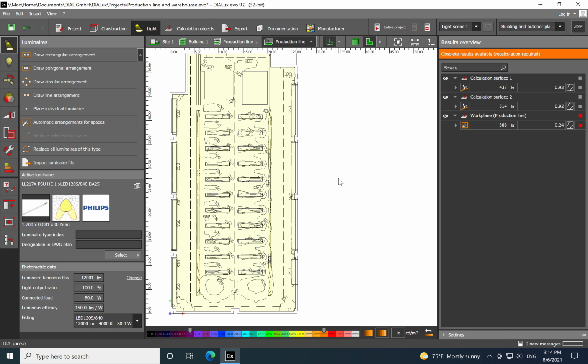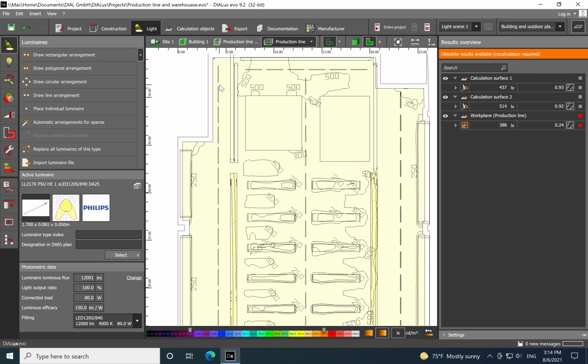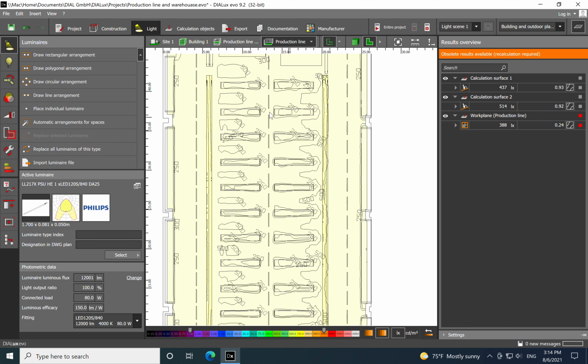In this case, when you increase the number of luminaires, the distance between two luminaires is decreasing, and because we have also the light level already shown on the lighting proposal, we see, for example, here we have 500. So here we are okay. Where we are not okay is on the shelf area. We see that we have 250, 500, 250. So here, yeah, definitely we need to increase the number of luminaires.